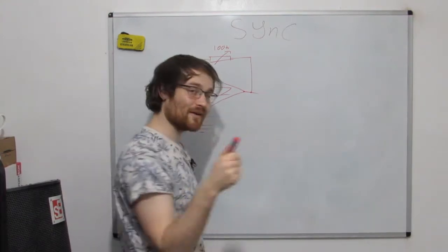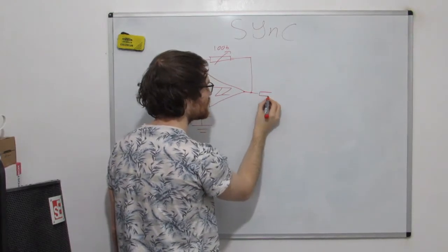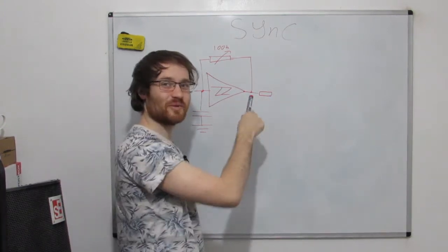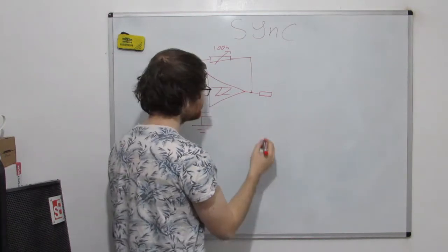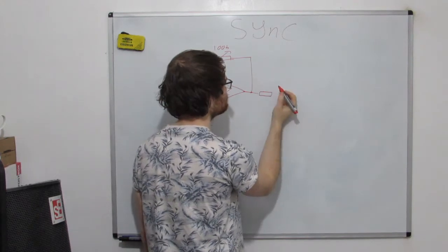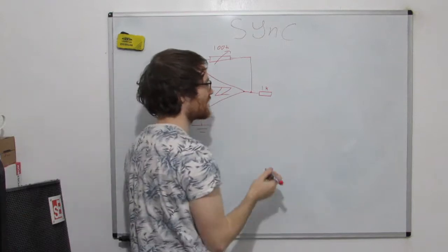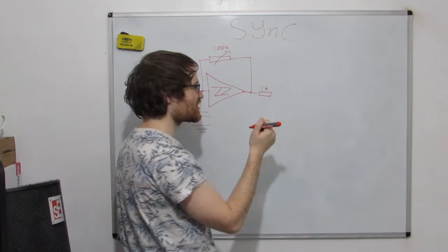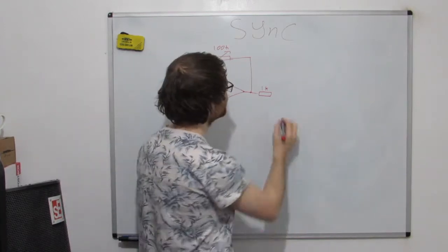And so what we're going to do now is put a resistor here. All this is going to do is limit the current output of this to make sure that the next chip doesn't get overdriven. I can't remember off the top of my head what it was on the board. Let's just say it's 1k. I think it's either 1k or 10k. It doesn't matter. You don't even strictly need that. It won't break without it. It's just a good idea to have.